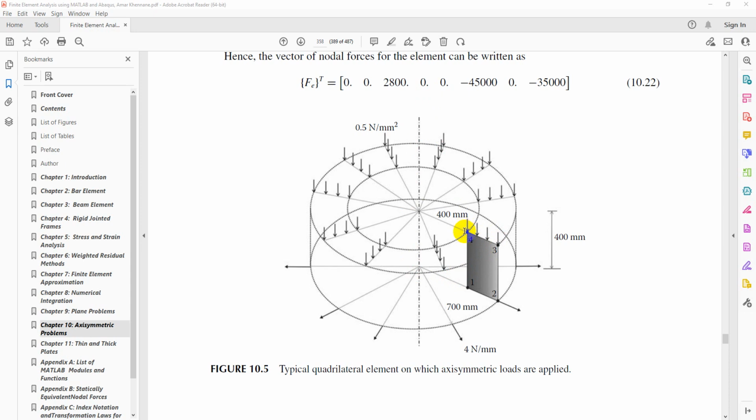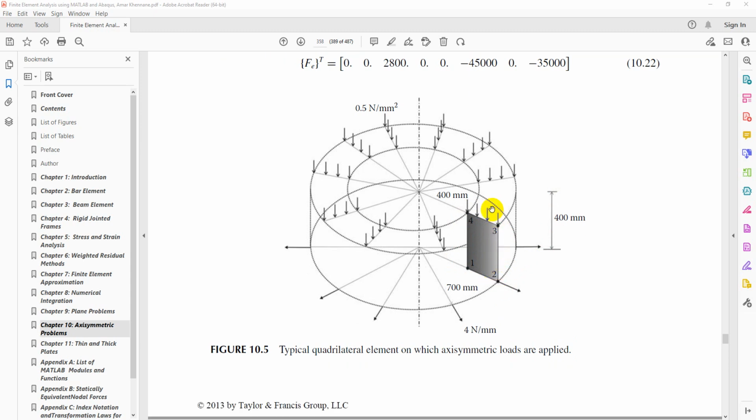So what is the usual procedure in FEA or in commercial software like Abaqus to solve this type of problem? Instead of modeling the whole of it, we just take out an element out of it. When that element is taken, it has a height and a width, so that a section has been taken and it can be modeled as a simple plate.